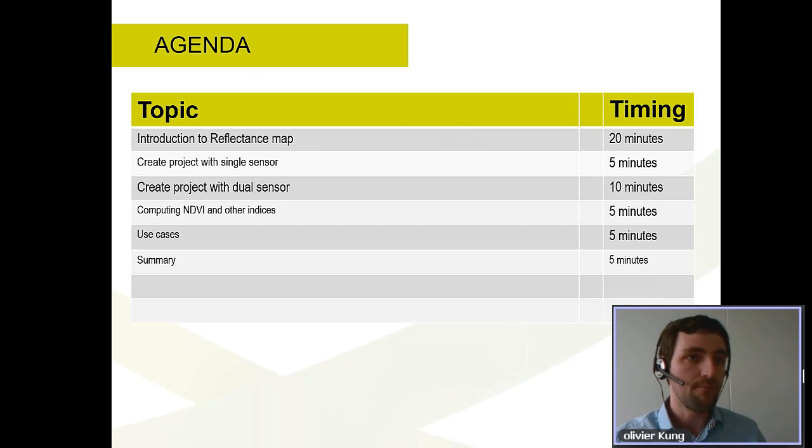Then I'm going to show step by step how to create a project when you have a single sensor in Pix4D mapper and how to extract potentially NDVI from it, and also present a way to create a project when you have multiple cameras in your UAV or on multiple UAVs.